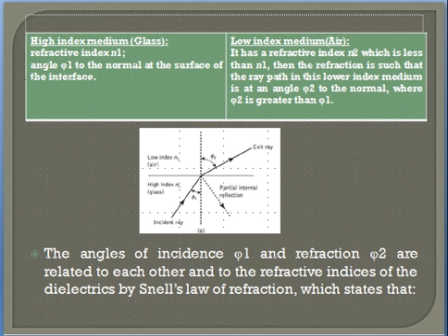To consider the propagation of light within an optical fiber utilizing the ray theory model, it is necessary to take account of the refractive index of the dielectric medium. The refractive index of the medium is defined as the ratio of the velocity of light in vacuum to the velocity of light in the medium. A ray of light travels more slowly in an optically dense medium than in one that is less dense, and the refractive index gives a measure of this effect.